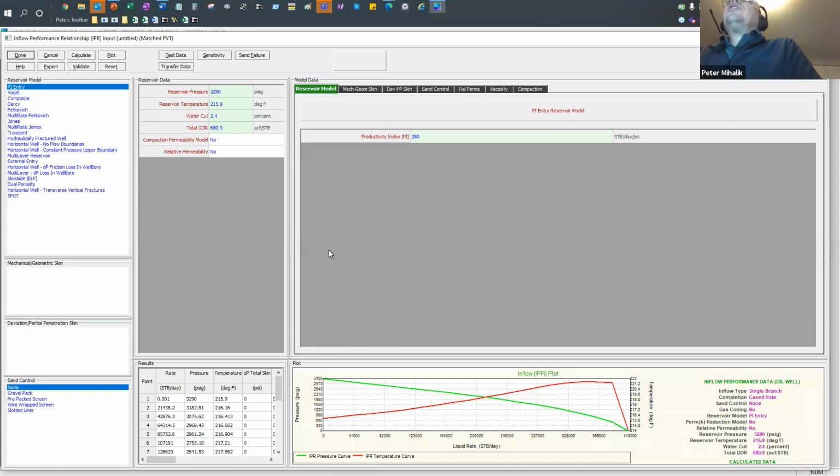Yeah, so let's say, for instance, you've drilled a new well and you want to bean up the well. Typically, you might be defining a bean up schedule. Let's say for the first 15 minutes or whatever, on the choke you want a certain amount of drawdown applied. And then over the next 15-minute period, it's a slightly different drawdown. And then after another 15-minute period, there's another choke setting change that allows you to apply a slightly higher drawdown.